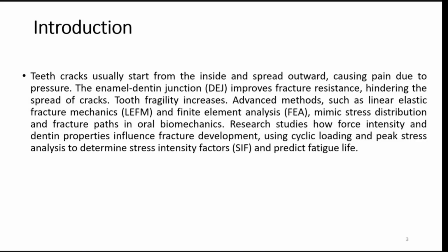Linear elastic fracture mechanics and finite element analysis are used to mimic the stress distribution and fracture path in oral biomechanics. This research studies how the forces, intensities, and dentin properties influence fracture development using cyclic load and peak stress analysis to determine the stress intensity factors and predict fatigue life.